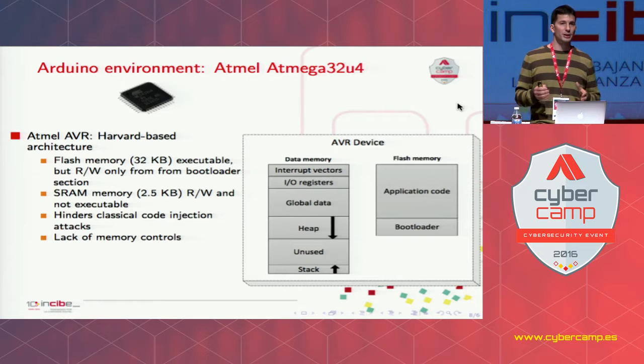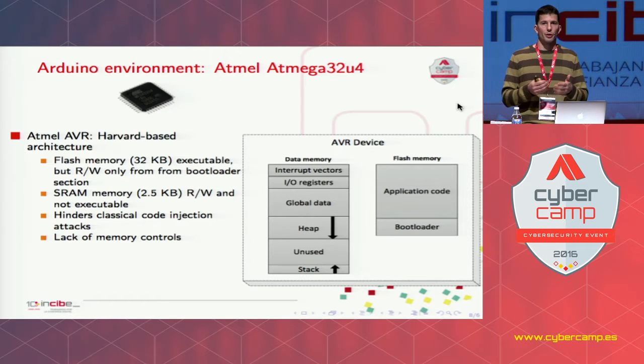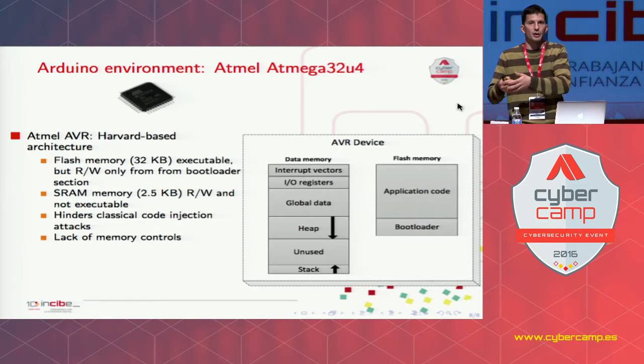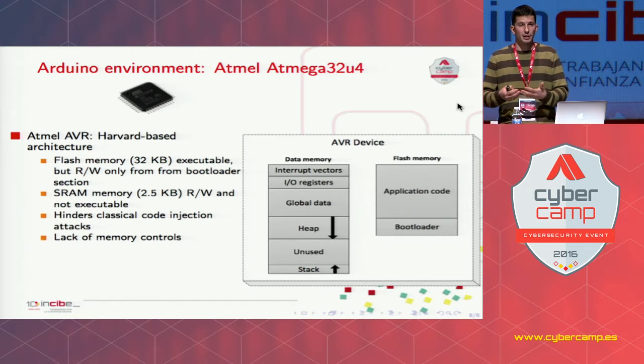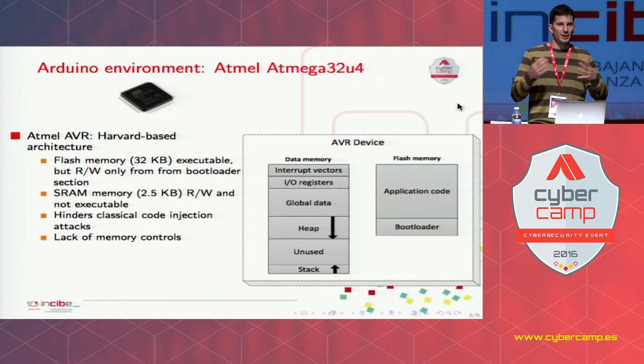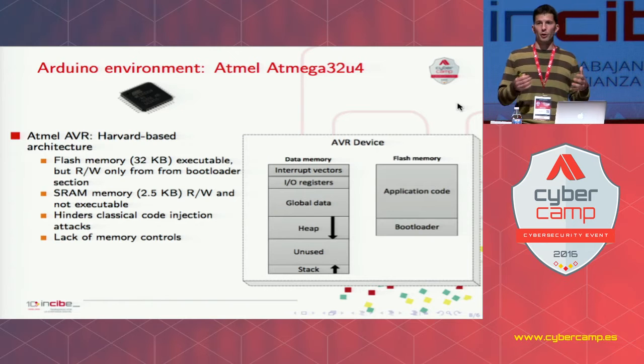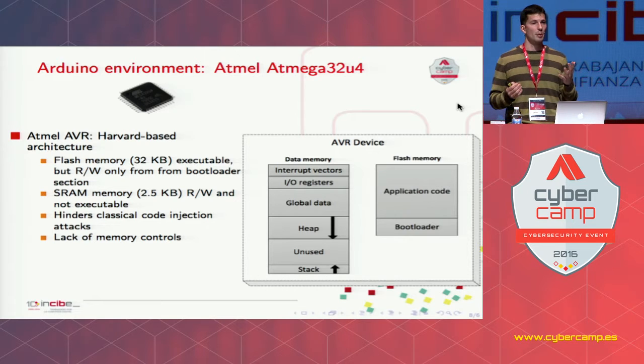So now moving on to Arduino, and I'm going to go deeper and deeper, going down and down. So we analyzed the architecture, which is AVR. This architecture, well, I'm sure that you're aware of x86, ARM, and this is a different one. It is based on Harvard. It's Harvard-based architecture. Those of you that study IT engineering, you know that this is not the Von Neumann architecture that we are taught at university. This is a different paradigm. It divides or separates flash memory from RAM memory. Physically speaking, both these memories are separated.